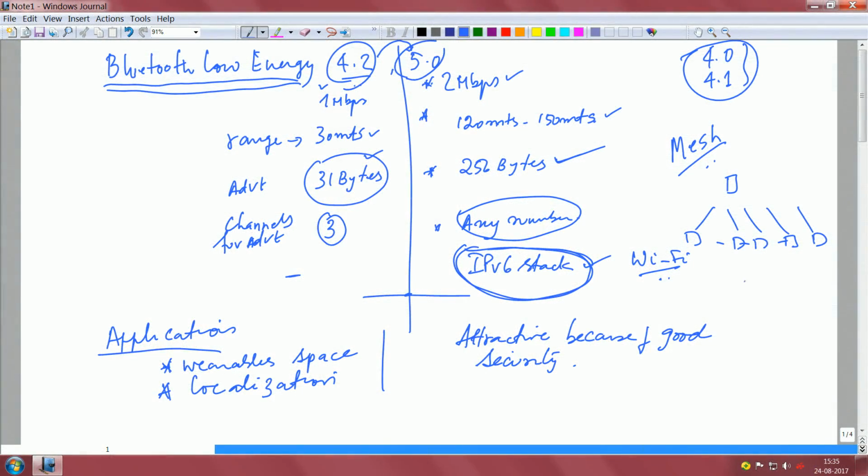So the contending protocols, the rich wireless protocols for the Internet of Things, will definitely involve BLE as a big contender for all small range low energy applications, and Wi-Fi, perhaps even low energy Wi-Fi, which might turn out to be a big advantage for slightly longer ranges. So do look out for BLE, and do look out for the way BLE 4.2 and above are shaping up for many of your applications.